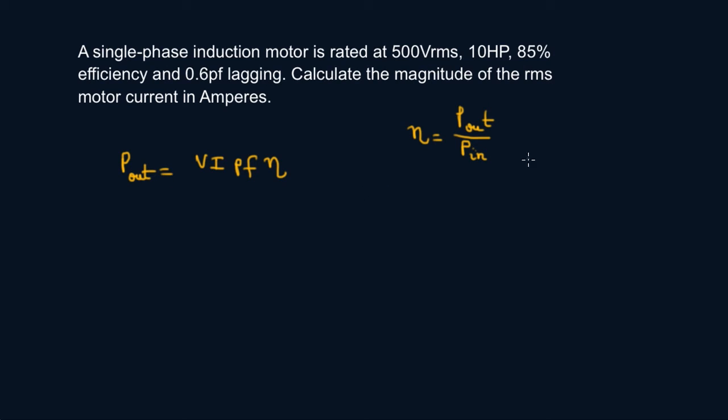Also, we have that 1 horsepower is equal to 746 watts. This is something to remember as well. I think it's in your FE handbook. I'm not sure if this formula is in there, but I've done a lot of PE problems where I needed this, so that's where I remember it. 1 horsepower is 745.6 something, so generally speaking, we use 746 watts. So this is the formula for your output power, your mechanical energy.